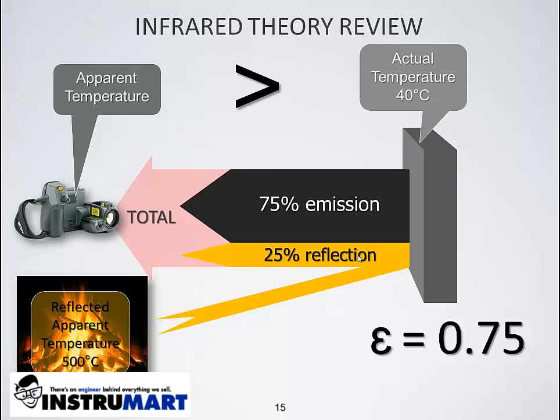Now, from these exercises, we learn that not only is it important to know the emissivity of the target, but it is just as important to know the temperature of the reflection source, or the reflected apparent temperature. Later in the webinar, I will demonstrate how to determine the reflected apparent temperature using an infrared camera. But first, let's discuss how you determine the emissivity of your target.